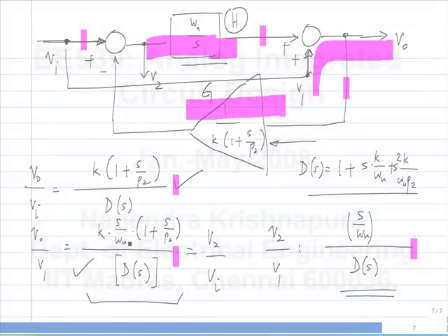Okay. In this particular case, it may not be interesting, but in some cases, you can get interesting transfer functions by feeding it at multiple points. Okay. An alternative thing is you can take multiple outputs and sum them. Okay, that also gives you sum of different transfer functions. So if you want to manipulate the zeros, that's what you do. Okay, you either first look for different points to inject the input, or different points to take the output from, or you inject the input to multiple points, or you take the output from multiple points and form a linear combination. Okay, so when you are forming transfer functions, this is how you do it, if all you are interested in is manipulating the zeros.